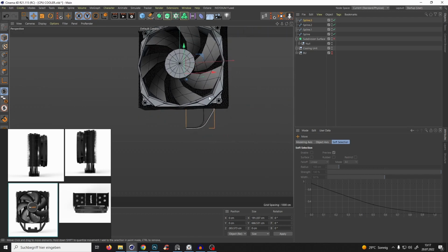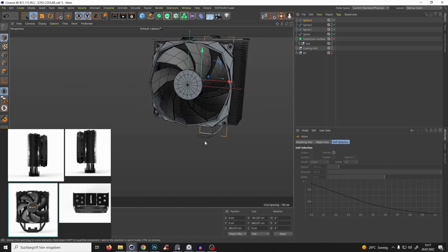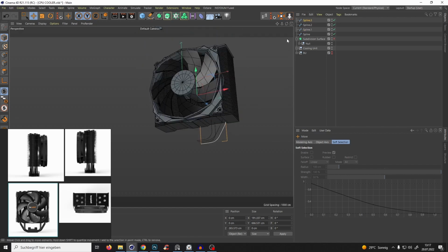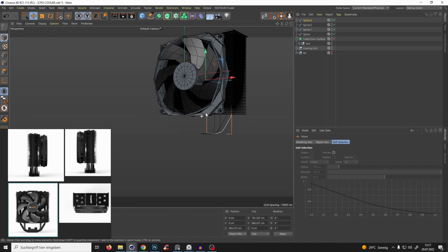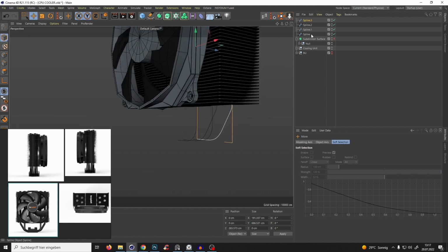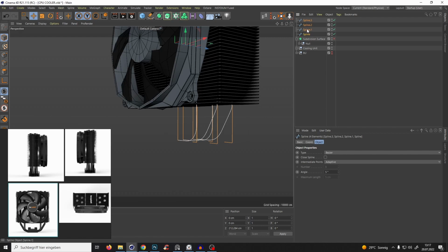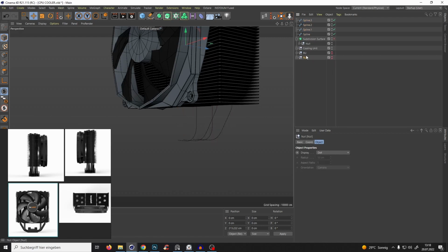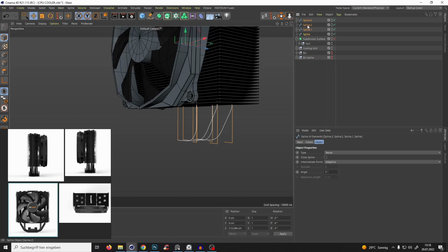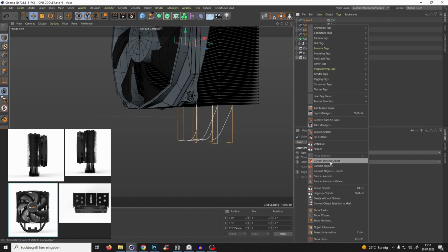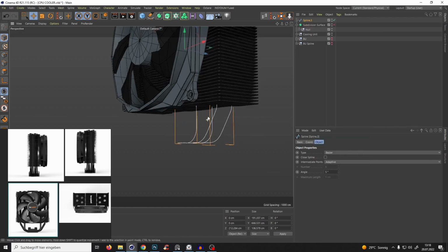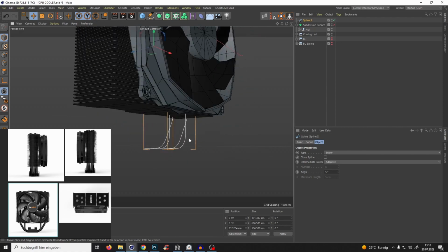And what we can do, we can either do this step, which I will do now, to give it geometry for either spline individually, or yes, in that case, I think I can just copy them, control click V, and bring them into a group to make a backup spline if I need them. But all those splines here I can connect into one kind of spline. So it's connect objects and delete. So one spline is every spline.